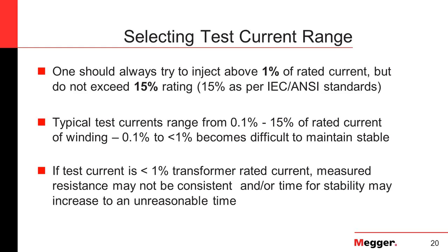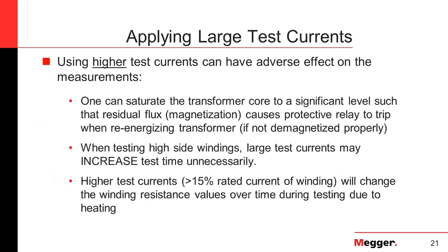But the truth is, if a transformer is built with that difference, then one must take a trend of what it was before and what it is now. And if it maintains that difference, then we know that even if it exceeds the 2%, but it was there when we first tested, it is fine. But for the purposes of this presentation, 2% is the limit. Okay, thank you. You're welcome.